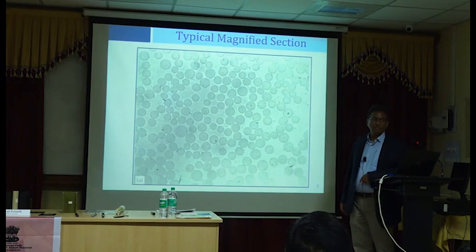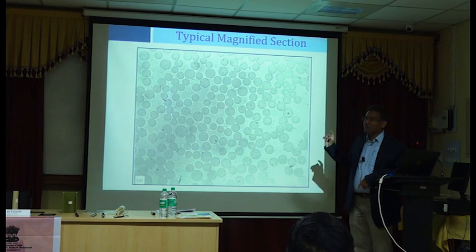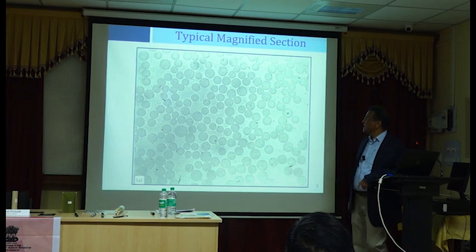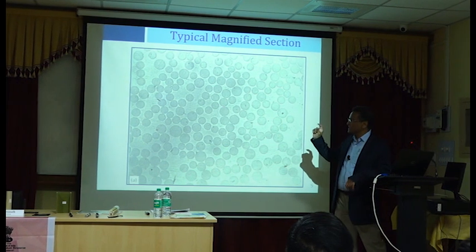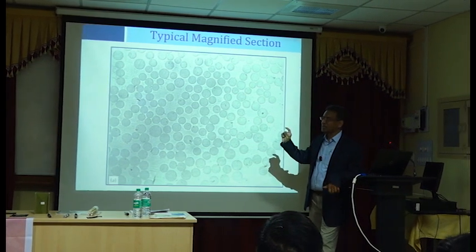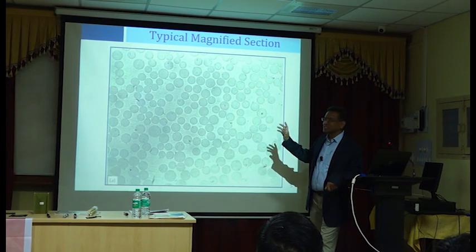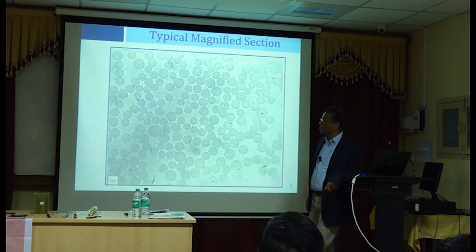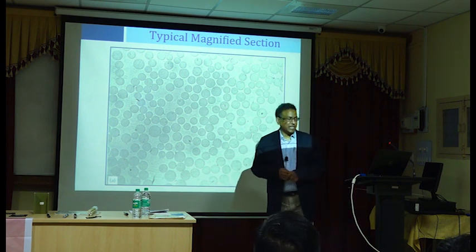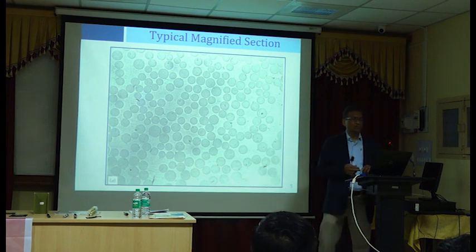Yeah. Not uniform. Fiber cross section is not uniform. Perfect. The diameter of the fiber is not uniform. You will see the diameter varies substantially. But we cannot consider that. We always consider average diameter and amount of fiber based on the total fiber, and we'll always work with weights rather than volumes. I will talk about it in a minute.